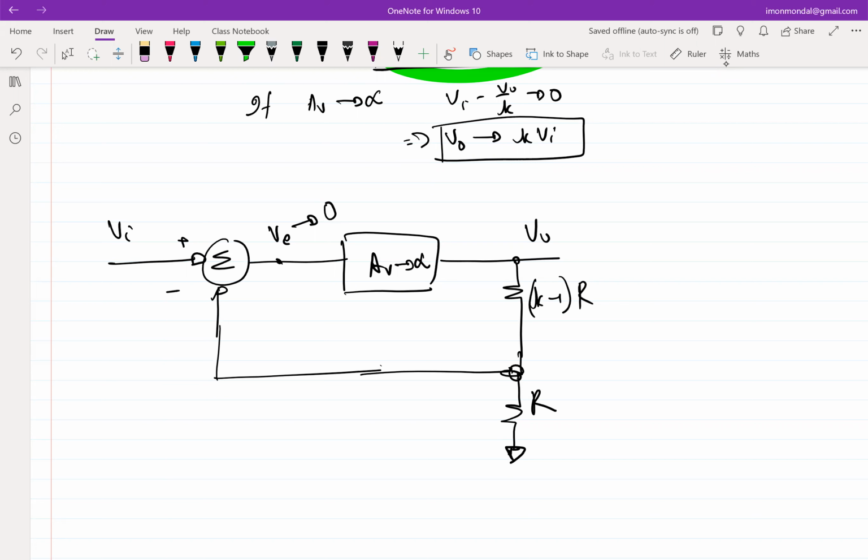You're looking into the network, the circuit or the system, and you have to figure out that if there is an error, let's say I am not going in the right direction, is the sense of the correction in the right direction? Which means, is the error getting magnified or is the error getting reduced? As long as I know the sense is right, I know the direction of the feedback is right. Rest of it is component values, right?